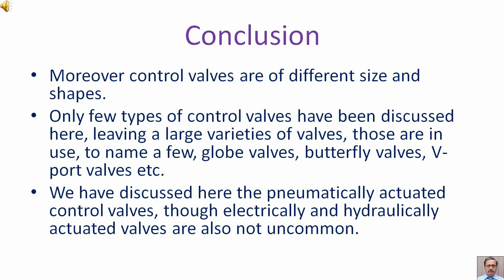Conclusion. Moreover, control valves are of different size and shapes. Only few types of control valves have been discussed here, leaving a large variety of valves that are in use, to name a few: globe valves, butterfly valves, V-port valves, etc. We have discussed here the pneumatically actuated control valves, though electrically and hydraulically actuated valves are also not uncommon.